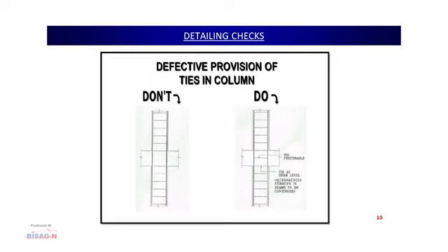The bar binders generally do this because the beam reinforcement would be coming from one side, so at this junction there is heavy congestion of the reinforcement. So, they think it is not advisable to give this tie, because there is heavy reinforcement here, and also it is very difficult to put the concrete and the vibrator inside during concreting. So, they feel it is better to avoid the ties.